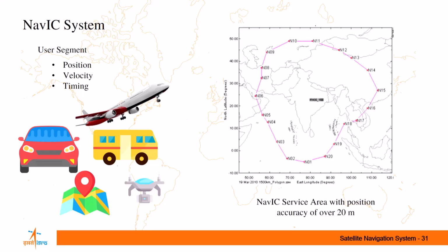Finally, what we are getting is about 20-meter accuracy on a very conservative side. If we use the IRNSS services, we will see that we are getting accuracies better than 10 meter also at various times when we are surveying. However, during the worst time also we will get very good accuracies of the order of 20 meter. Normally when we survey in the afternoon, the ionospheric activities are high and we have a higher DOP, which indicates a bit poorer quality of the signals.